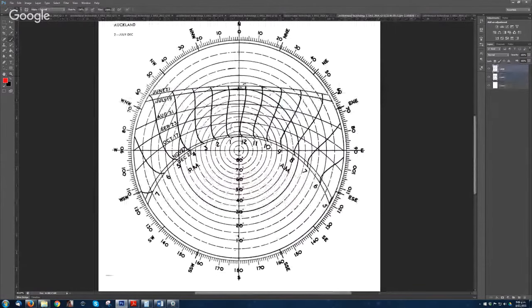So the first question: July 19, the sun position and altitude for 9 o'clock, solar noon, as shown on the chart. So July 19 is this line here, 9 o'clock a.m. is this side. You go here and make that line.